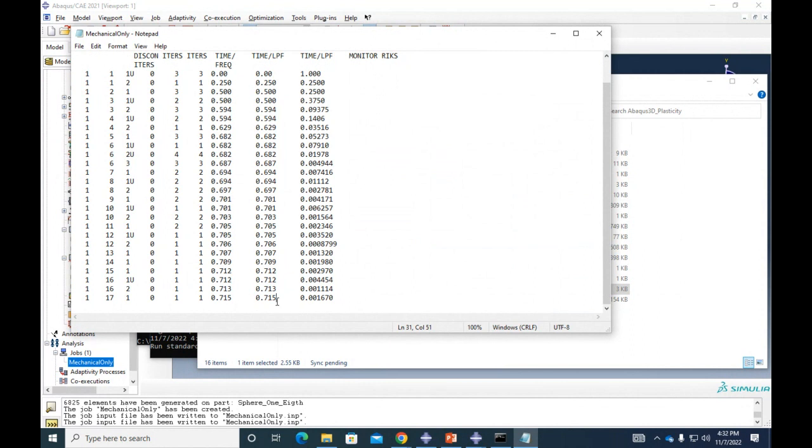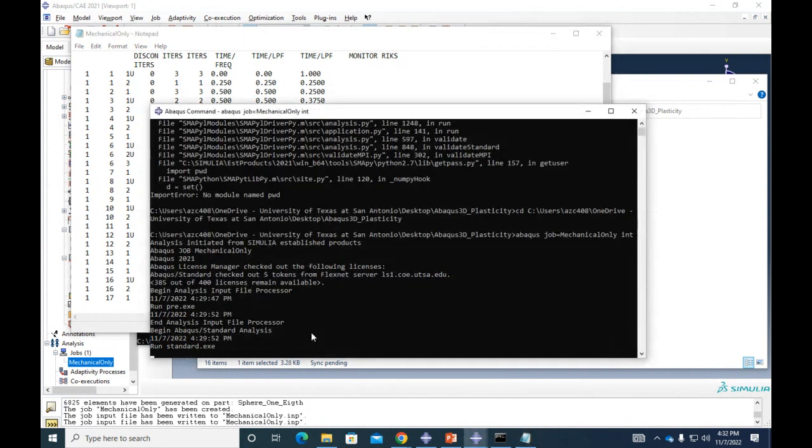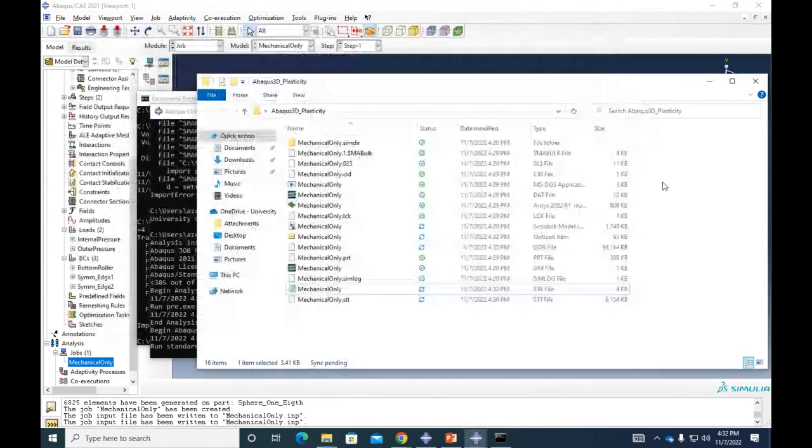2, right? The initial 0, 0, and then the final, which at this load, you get this amount of displacement. Here, Abaqus has to break the load, the pressure that I'm applying, into small increments. The reason is that once you achieve yielding in your structure, you have to start adding the load little by little, because you have to recompute the amount of plasticity each time. So it's an iterative process, and that's why the simulation is taking so long. It's taking a long time.